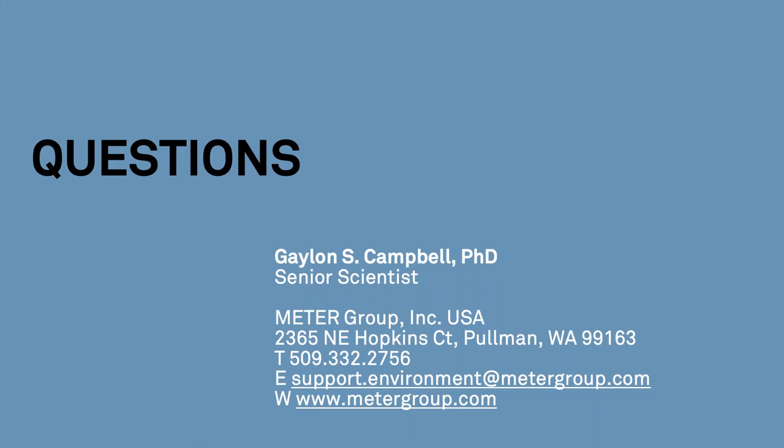If you're not irrigating enough, you'll see that you never get back to field capacity, and that the average water content's going down. And so it's kind of self-correcting in that way, that you always will know as you go along and see the result of the decision that you made. You'll know what you need to do to adjust whatever factor you had to estimate.